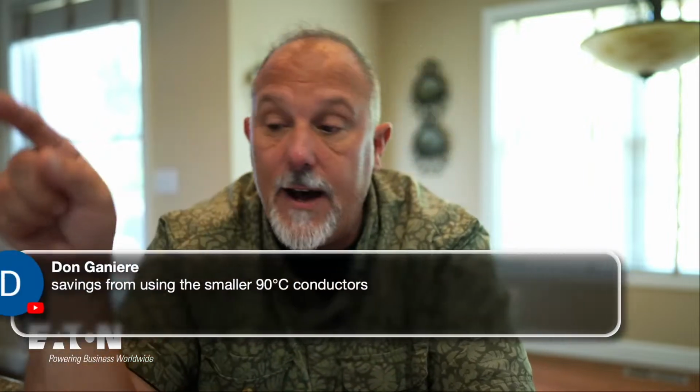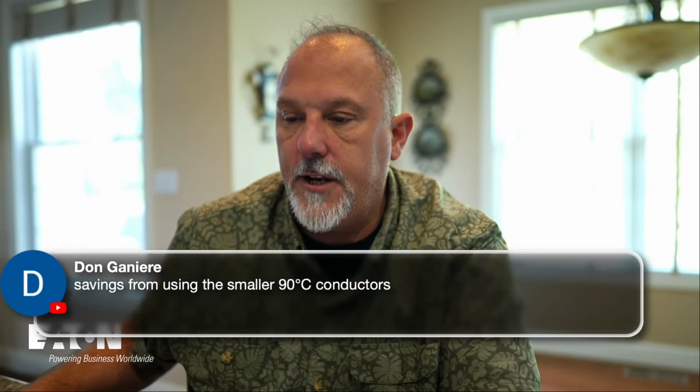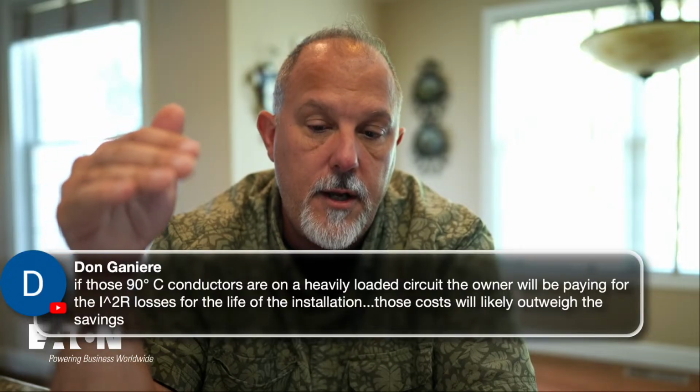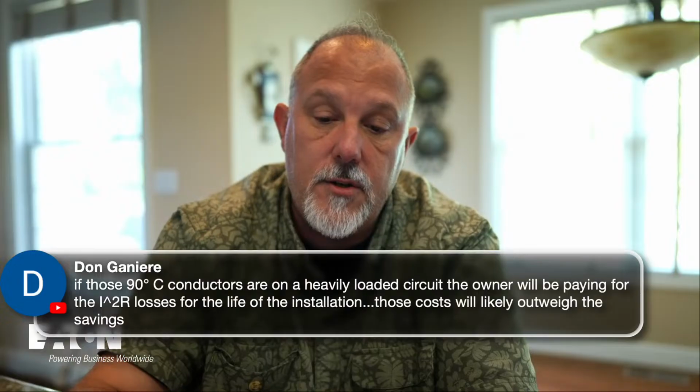Could I get away with a 10 amp circuit on those lights outside? I would have to say yes. Am I going to have an issue? Your point is valid. Your point is very valid that it saves us from using the smaller 90 degree conductors. Your other point was valid that if you heavily load those, then yes. But I have a 20 amp circuit going to those outside lights.